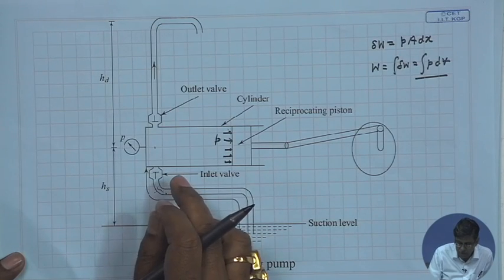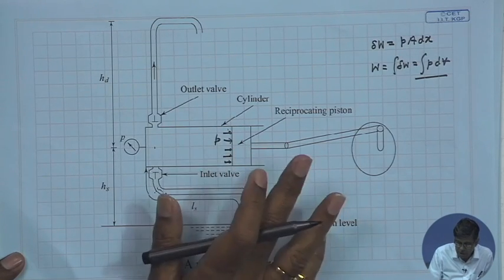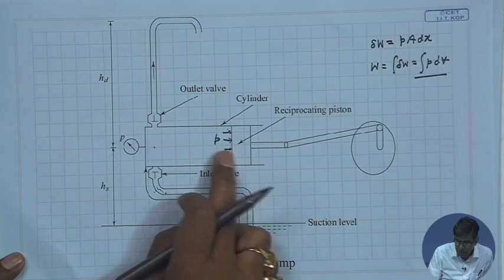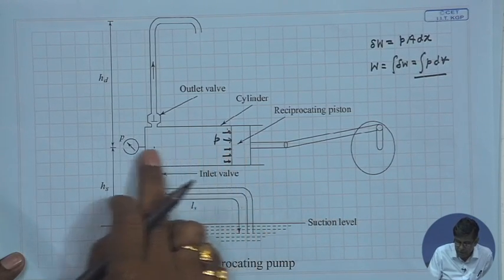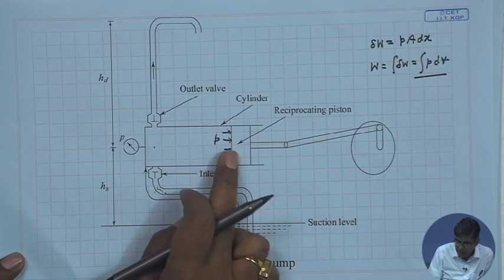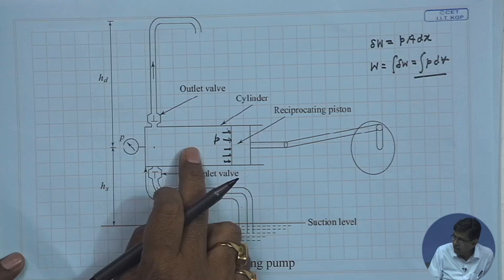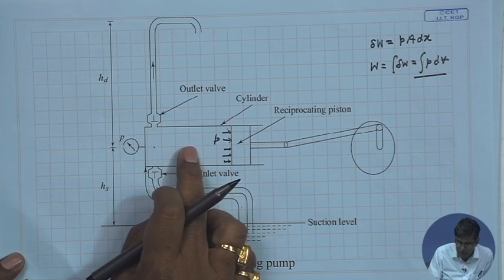So, therefore, during the suction stroke there is zero delivery rate, and during the delivery stroke there is a delivery rate, but it executes a simple harmonic motion. Initially there is acceleration and then deceleration, resulting in a maximum velocity at the middle of the stroke.